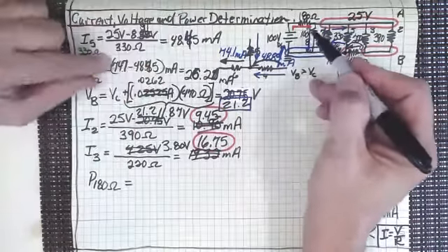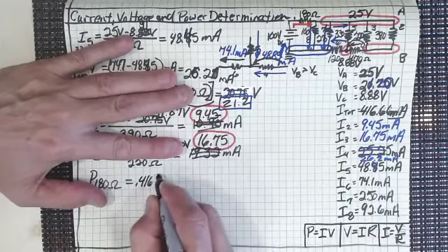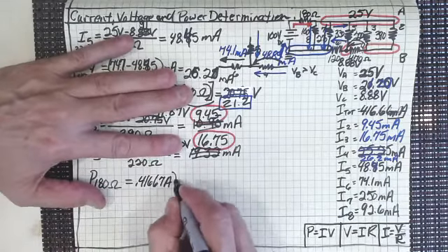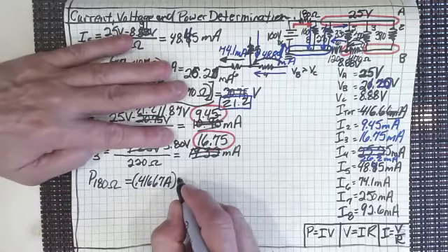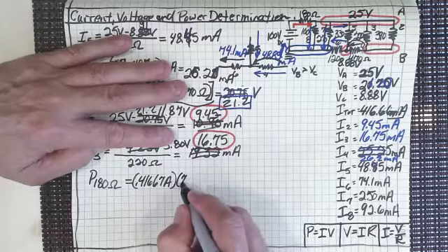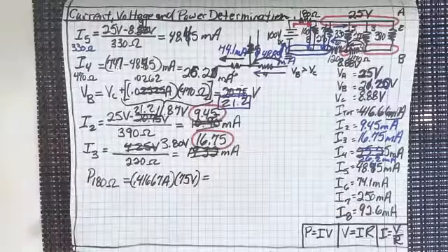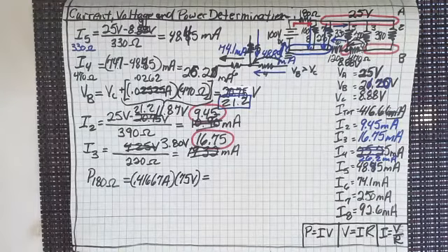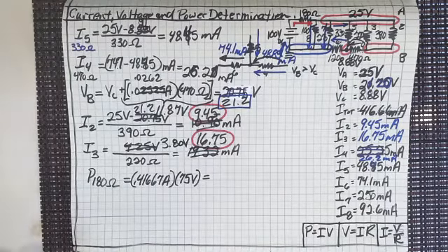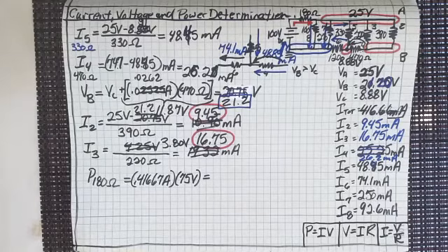So if we look at the amount of current, that's the maximum current going through there. So that's going to be 0.41667 amps flowing through there. And we know the voltage across that is going to be 75 volts, the largest voltage differential in our entire circuit. And the real question is, is that going to be more than 1/4 watt, right? Volts times amps equals watts, that's right.